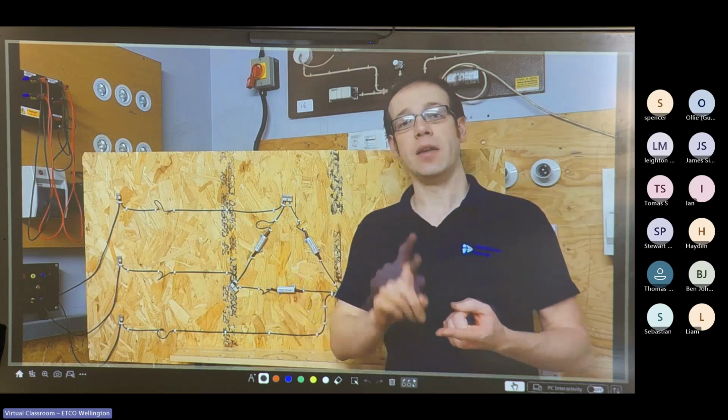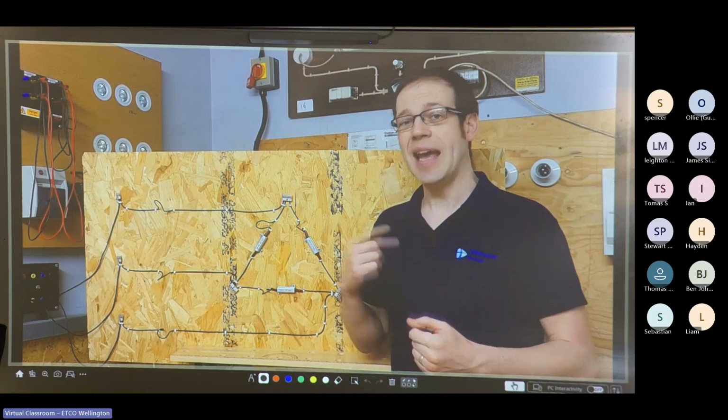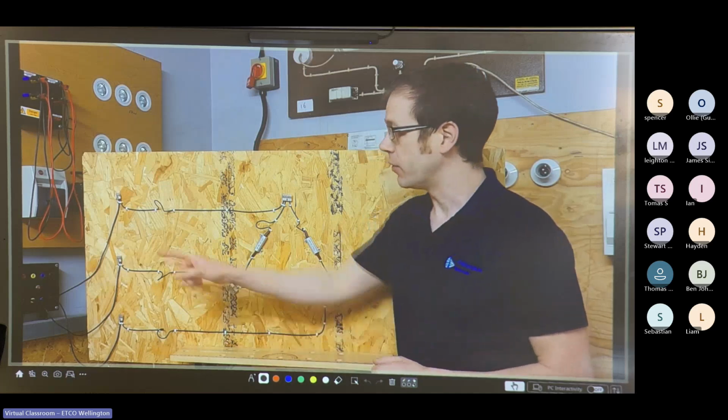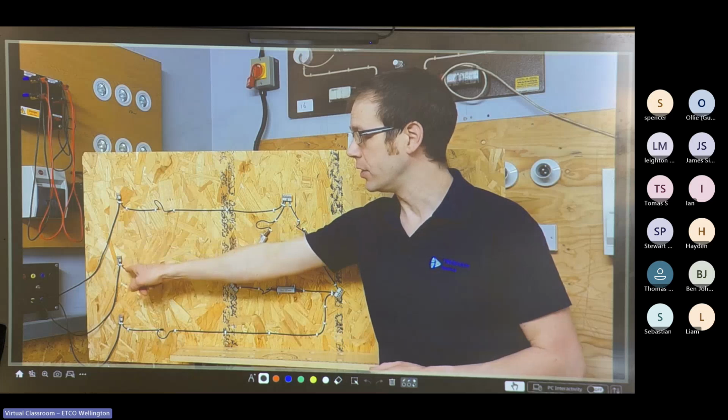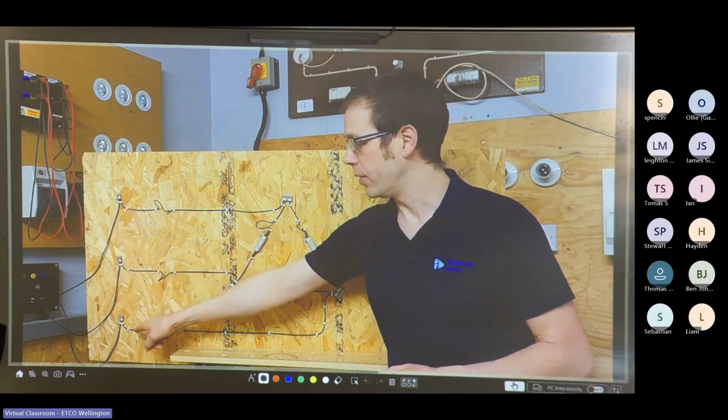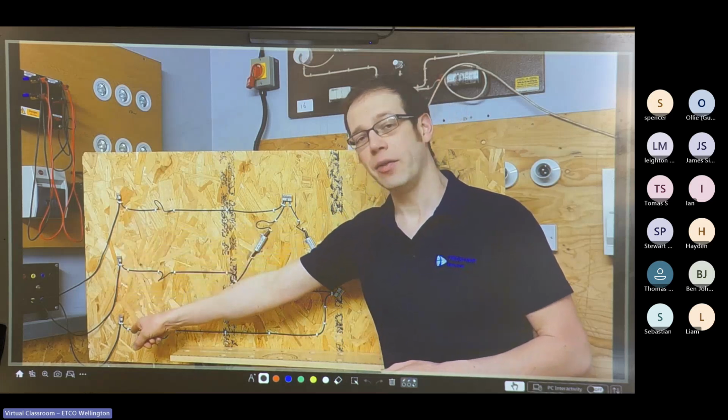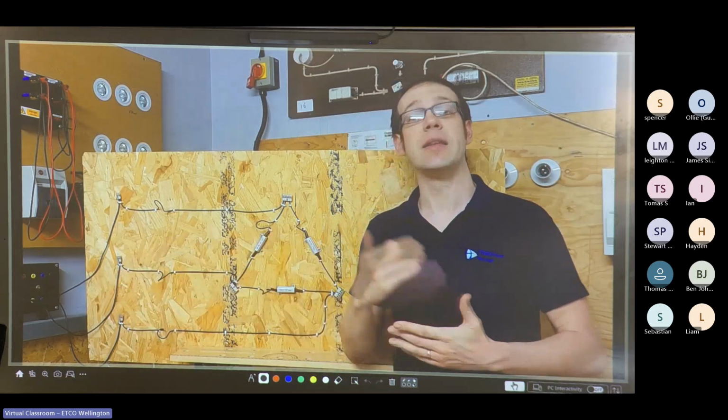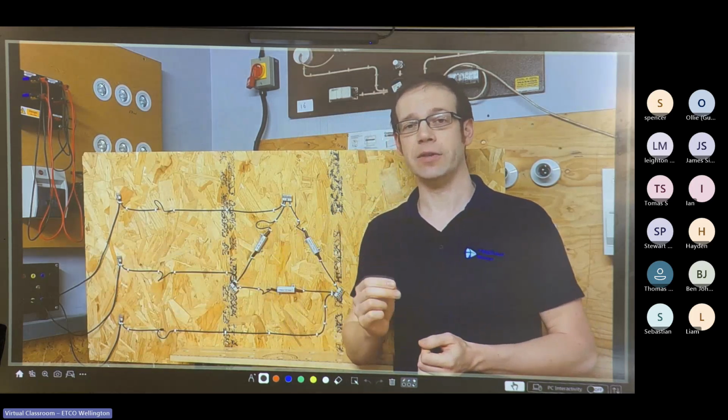The line voltage is the voltage between any two supply lines. That means we can measure the voltage between L1 and L2, or between L1 and L3, or between L2 and L3. They will give us similar readings. We will get the line voltage.